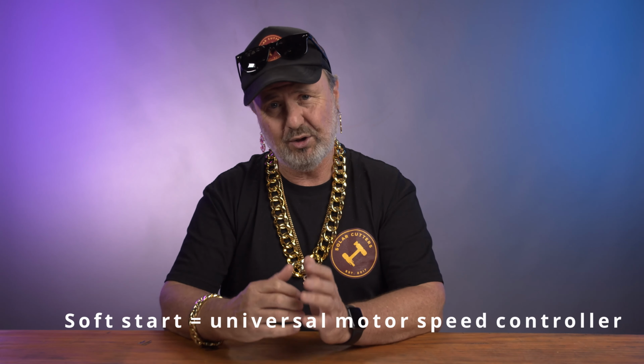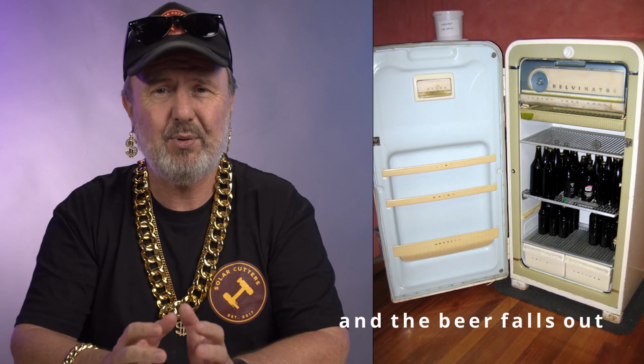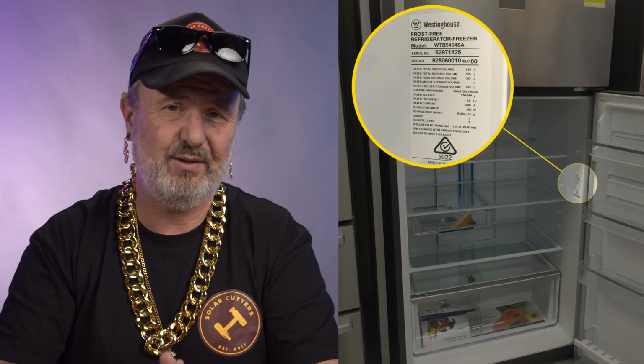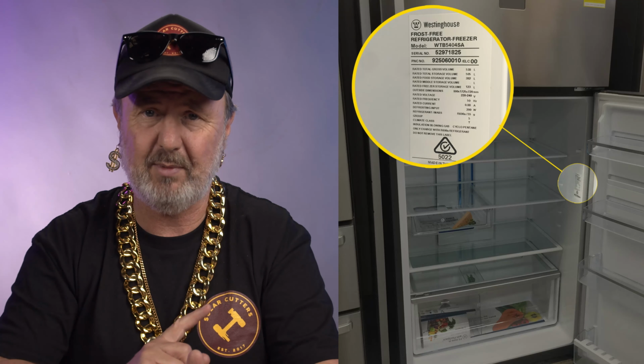But if it's a really old cranker, one of those ones you have to use two hands to open the door and it just about flies off the wall, it's probably got a reciprocating compressor, which has quite a high startup current. Anyway, how do you find these things out? The compliance label doesn't tell you any of this. It'll just tell you, it might say amps, it might say watts.